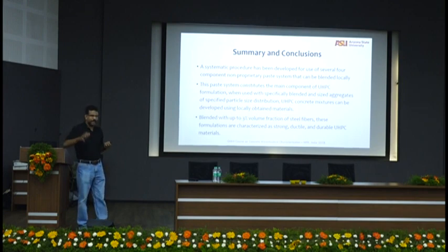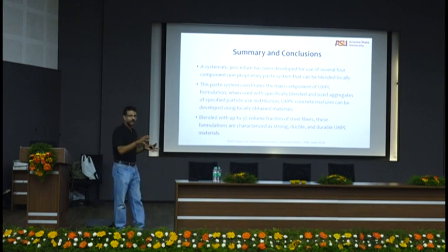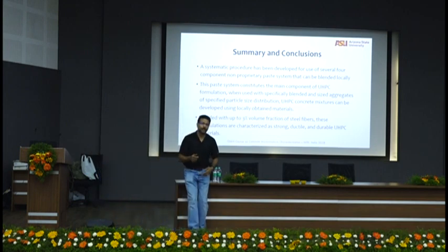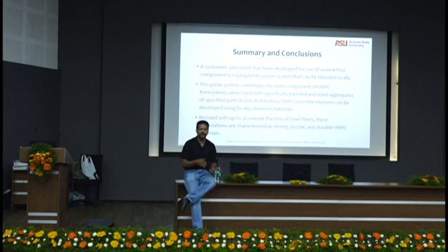Okay? So some of the ideas that we talked about in the morning: particle packing, implementation of all of that in the natural structure. And the quality control has been extremely good. Quality control in the US is typically not a problem for concretes. But in this case, we had to have some additional measures for packing, so we had to check the particle size distribution for all the raw materials that were coming in to make sure that they get the predicted strengths that we told them that they'll get.